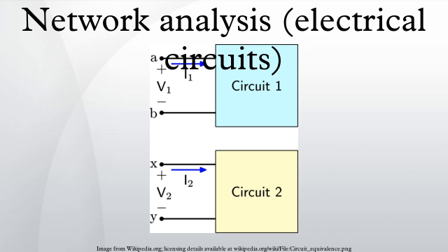However, if a network contains distributed components, such as in the case of a transmission line, then it is not possible to analyze in terms of individual components since they do not exist. The most common approach to this is to model the line as a two-port network and characterize it using two-port parameters. Another example of this technique is modeling the carriers crossing the base region in a high-frequency transistor. The base region has to be modeled as distributed resistance and capacitance rather than lumped components.